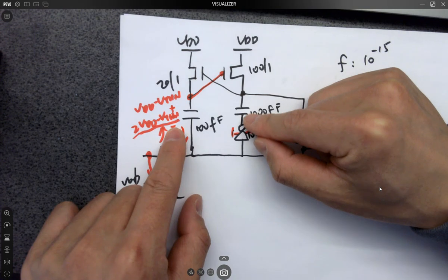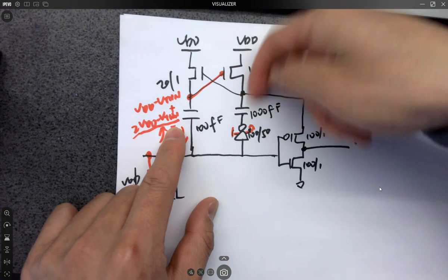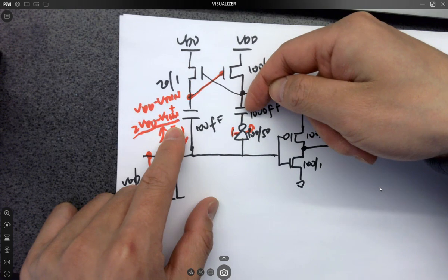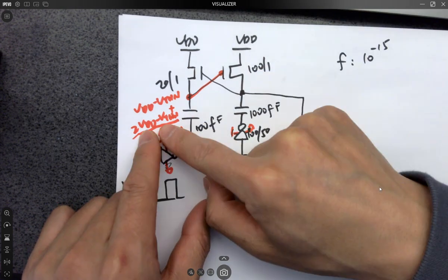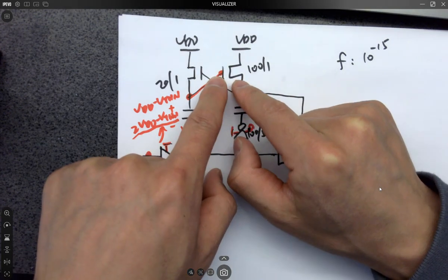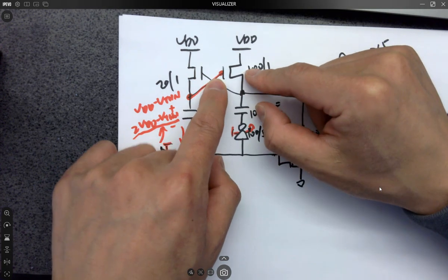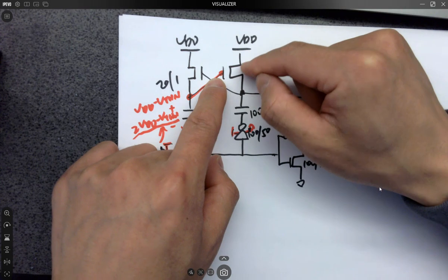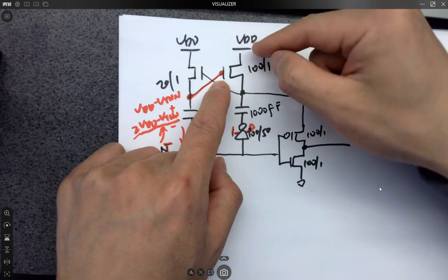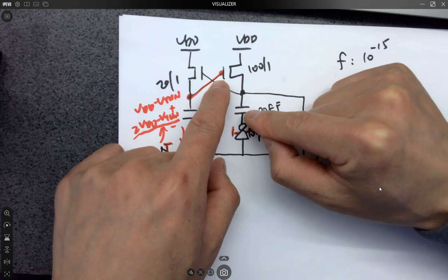And this is pulling. So when this is pulling, it's doing what? It's charging up the cap from the VDD. It's dumping charges from VDD to this cap. That makes a lot of sense because whenever this is being pushed to the higher voltage and shorted to the gate, you are getting a higher voltage at the gate, which will be able to widely open this NMOS, just open it wider, and which is able to pass the entire VDD to the cap because this guy is pulling.